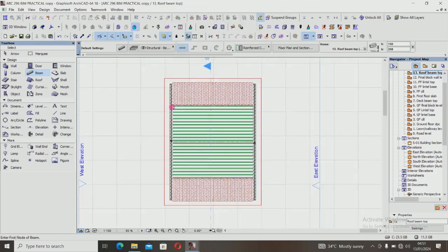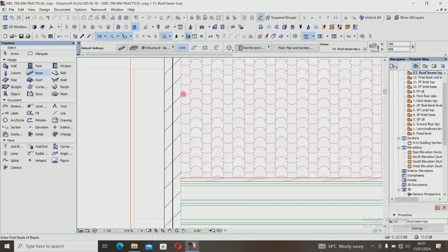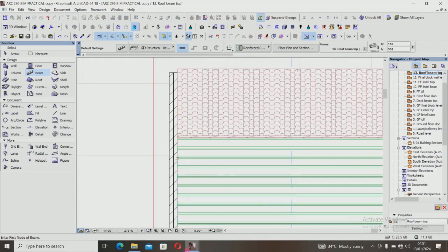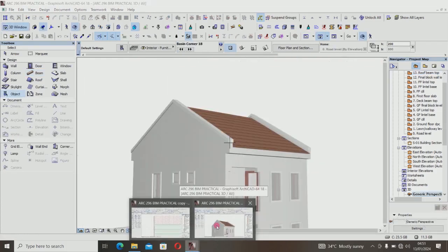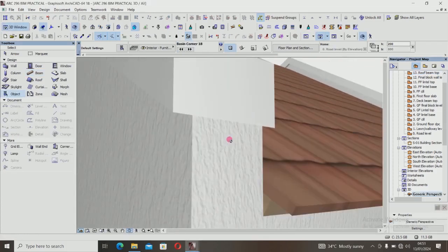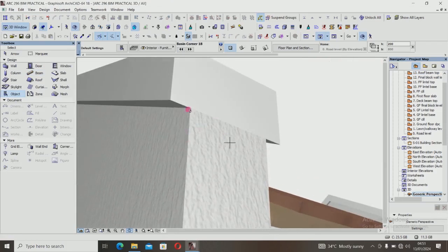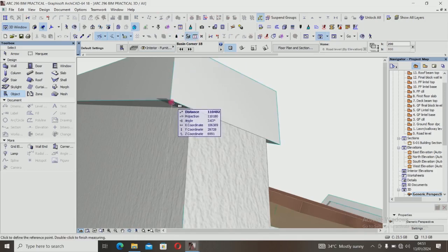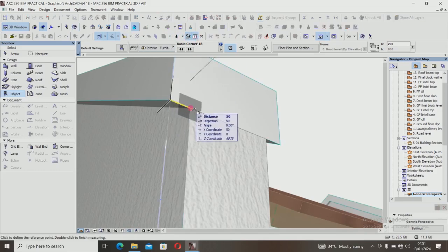Before you do that setting, this wall is 225 thickness. If you check in our previous model here, you see that this cap has an offset from the wall, an offset of 50 mm this way. Let me free it so that you can see it. Measure it, from here to here you can see a 50 mm distance. The same thing with here.